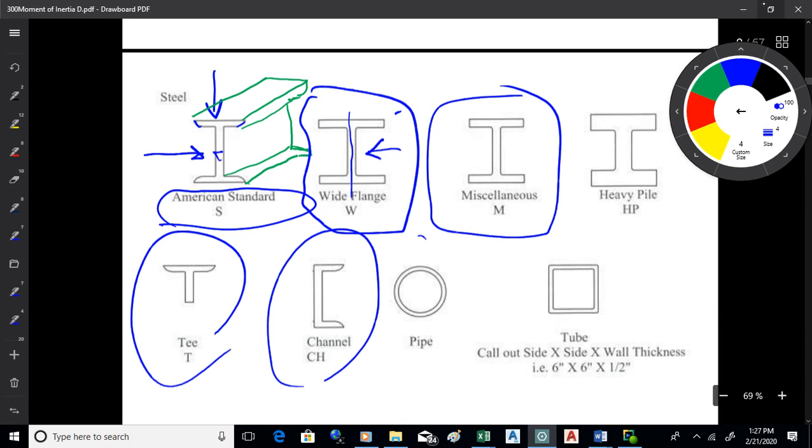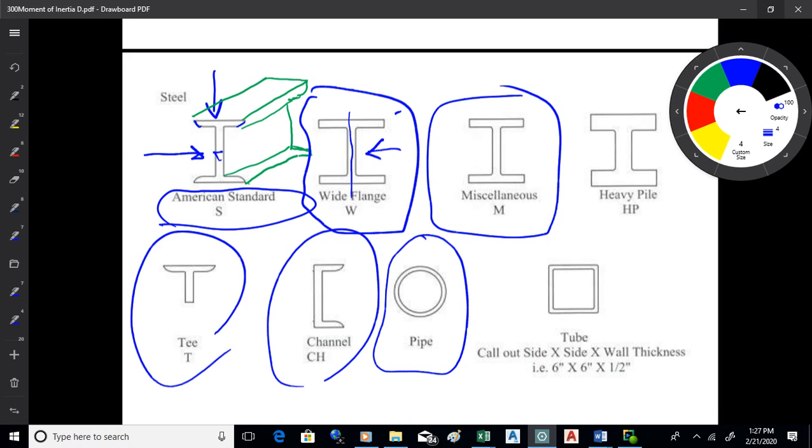So the common things there are pipe, and there's different types, but they use schedule pipe, you know, like a plumber type designation on that. They also use other types of pipe, and they make tubing, which you take a plate, you just bend it into usually a square. A nice little trick on columns is you put the column in there, that's the metal pipe or tube, and fill it up with concrete to stiffen it up.